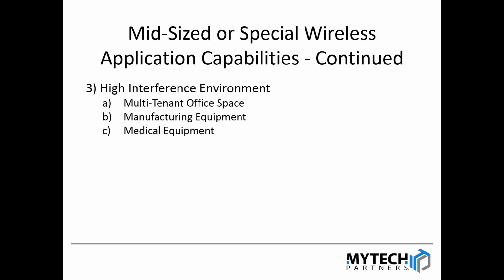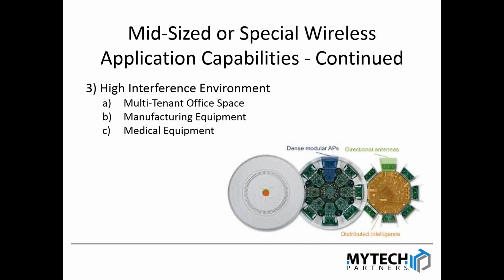But some examples of what we mean is, unfortunately, radio waves are a shared space, and there are open licenses provided by the FCC, and they give us a finite number of radio channels and a finite amount of radio space that we can operate in. In this country, for the purposes that we need, those tend to be in the 2.4 gigahertz range and in the 5 gigahertz range. And within each of those radio frequency allotments, there's a finite number of channels.